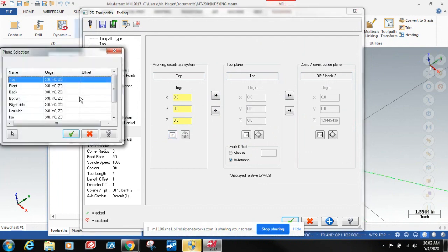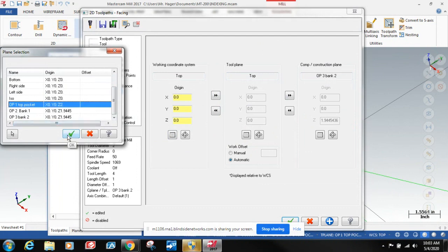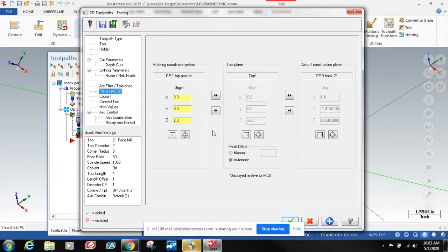You know, it looks like we should make more than one pass here because we're getting a lot of the face mill into the part with just one pass. That's what I'm thinking too. I don't know how high I need to go. That's the problem. I was just going to cut it into 2 passes.